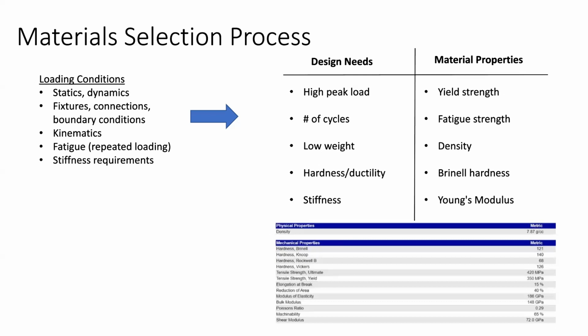When you anodize the surface, you produce a really small layer of oxide on it that's like ceramic. So that interface is relatively hard, but the inside is still somewhat ductile. The reason that matters in a center lock is you have a lot of vibration going through it, both radially as well as supporting the moment load. So you don't want it to be brittle, that would be really bad. So you get the benefit of, as you said, avoiding galvanic corrosion because you don't have a metal-on-metal interface, you have ceramic. But you also have the fact that it won't gall or damage the surface because the surface itself is hard.